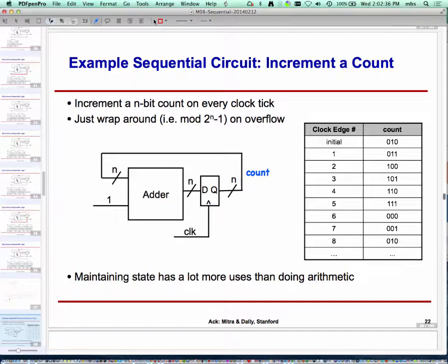So let's look at a circuit where we have an n-bit D flip-flop, which is nothing but n 1-bit D flip-flops with all their clocks tied together, with the n bits of our data bus feeding into the different D flip-flops, and the output again n bits, and it feeds back to an n-bit adder at the input.